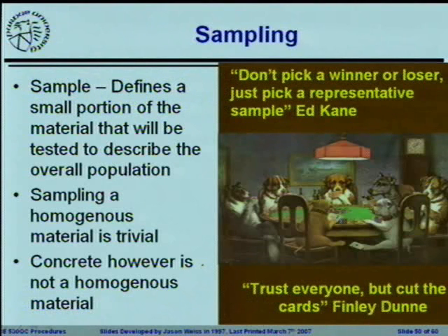Sample defines a small portion of what you're trying to take. You're looking into the back of one of these trucks. I will tell you, I would go out there with my little 4-inch scoop, my gloves so I didn't burn myself on the asphalt. I would look at 23 tons of asphalt, and I would try to put my little tiny candy scoop in there, and pull out a representative sample.